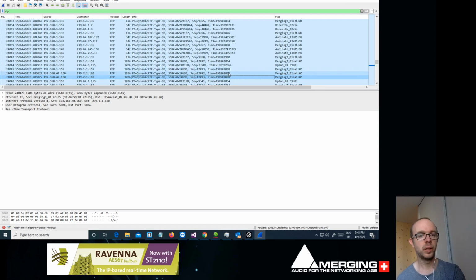And here on the multicast, the time value is incremented by 24. So this means that basically I have 24 samples in this packet, and then the timestamp will be 24 more in the next packet. All this information, or most of this information, you can find as well in the SDP that we saw yesterday.